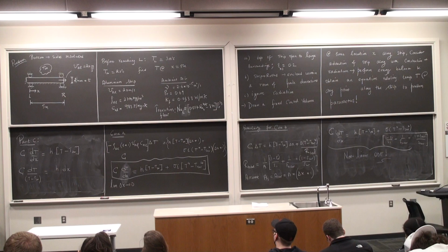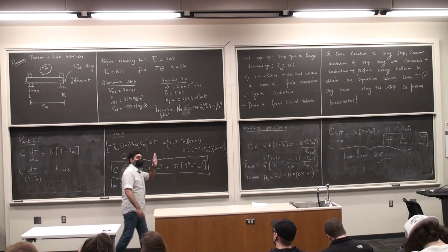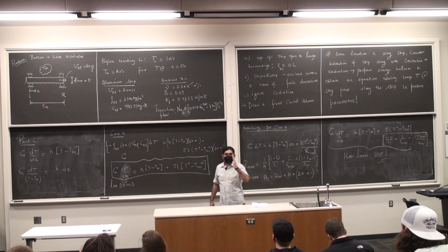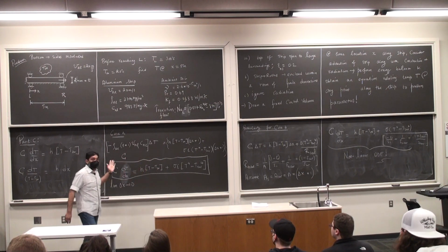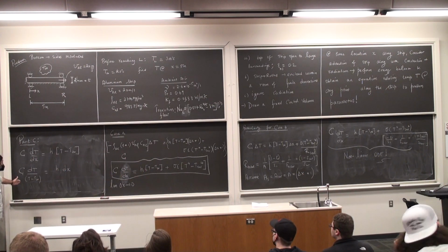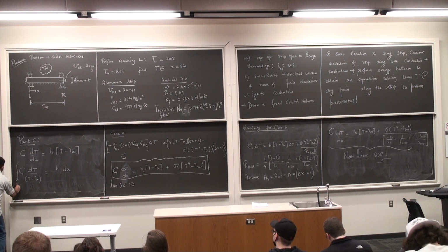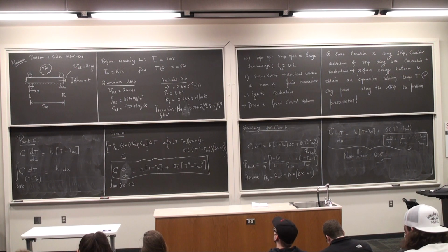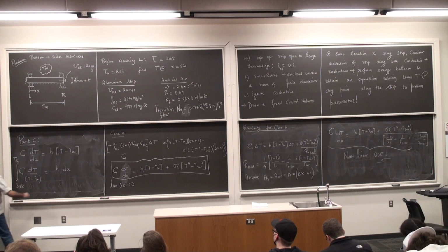What we are doing here is the following. We are saying, this strip saw the leftmost roller at a temperature of 300 degrees Celsius. It is passing through all of this particular length. So the integration on the left hand side has to be between the starting temperature of 300 degrees Celsius as it sees the leftmost roller to the temperature at the rightmost roller. And the integral on the right hand side is from 0 to L.